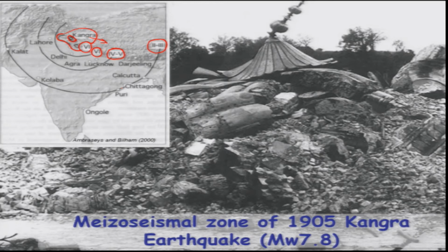Okay, so this is the intensity scale, and what we are looking at are termed isoseismals. Okay, so this indicates that all this region along this line had almost a similar type of damage which they experienced. So you can see that. Okay, this is very similar to the contours which we see for topographic heights, but these are not topographic heights; they are based on the similar pattern of damage experienced along this region.